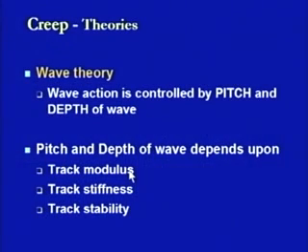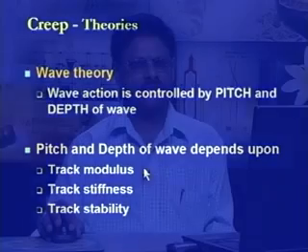It means we have to look at certain conditions by which the track modulus can be increased. The track modulus, as we have discussed previously when we discussed the stresses and resistances in the permanent way sections and its components, is one parameter which tries to define the strength of the track. So, if there are certain ways by which the strength of the track, or the track modulus, can be increased, then obviously we can reduce or control the pitch or the depth of the wave.